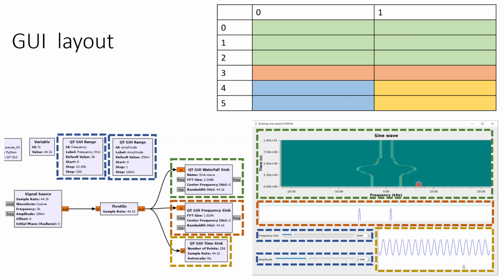And so then we create that table. The important thing to note for GNU Radio is that when we tell it how we want these components laid out on this table, GNU Radio wants things to start at 0, not 1. So when we start indexing our table, we say this is the 0th column and not the first column. And this will be column 1, even though it's the second column.